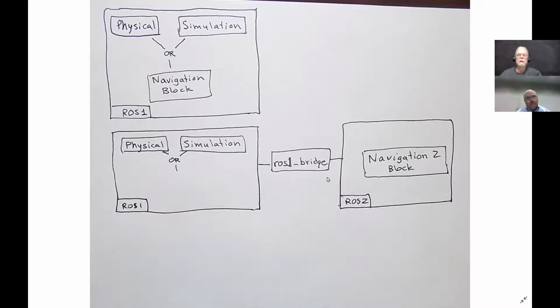And now when I jumped to load the stuff where I could run ROS 2, I now have Ubuntu 20.04, and I have ROS Noetic for ROS 1, and then for ROS 2, I have ROS Foxy. So when I did that, basically I jumped from Kinetic to Noetic. And now the laser scanner, I was still able to compile it for ROS 1, but I don't think I'd have any chance to get it to compile for ROS 2. Now, if I really wanted to, I could probably go down the line and try to figure out how to translate it or try to write it from scratch. But it's just easier to leave it over here in ROS 1 because it runs there and that will work.